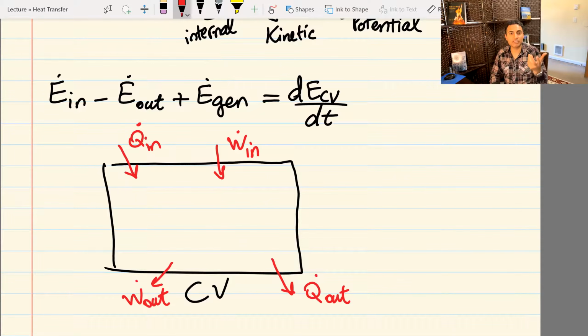You can have a piston cylinder system, which is a closed system, and you can have work, where the piston can expand and move an object and do some work, and you can heat it up also. That's heat transfer. None of these cases used mass of the fluid to enter the system or to force it out of the system. Does that make sense? This is very important and is a common mistake.